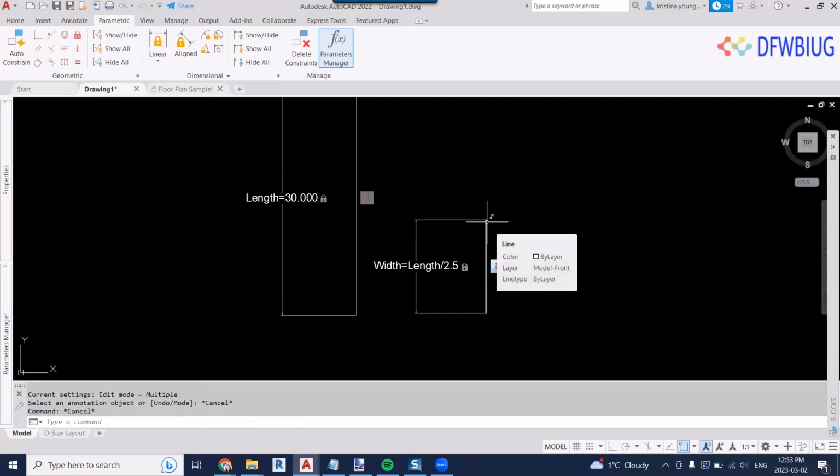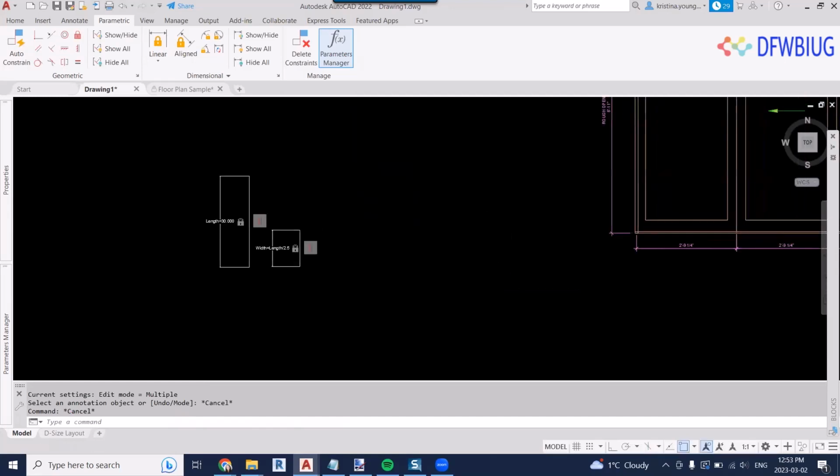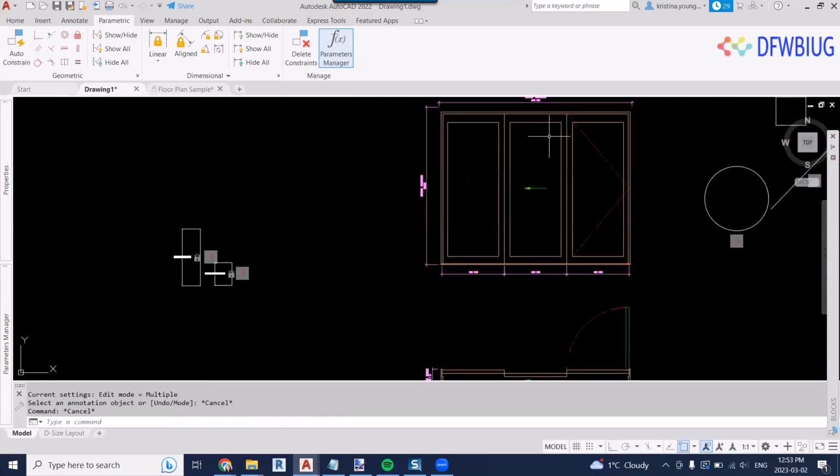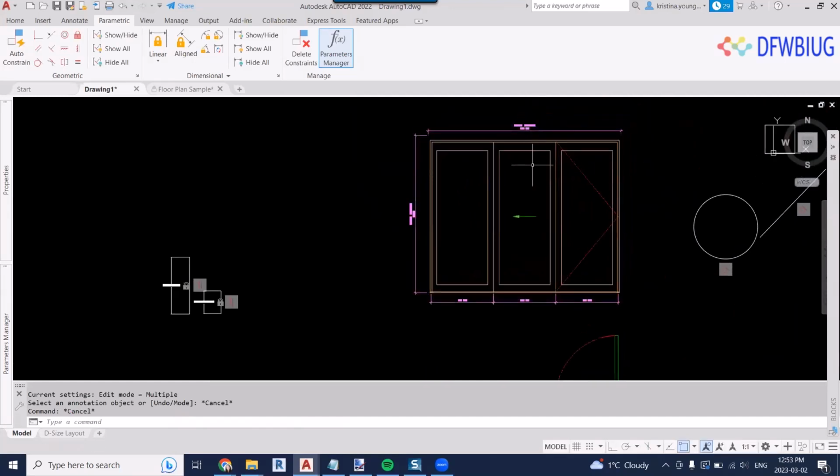Again, really good for details and for product development, because now I can actually convert this door to be a parametric door. I can add one of these dimensions here. This is going to be a future webinar, so I won't get into it right now. But I can fully parametrically dimension this object, associate the frames with the proper dimensions. So, your frame depth, your frame width, your clear opening, even your sill height.